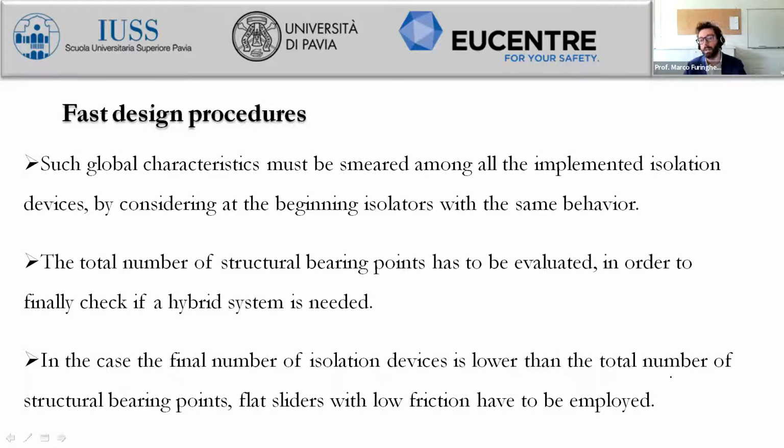So this means that we will have the same constitutive law, which means the same hysteretic rules, and the same mechanical properties and the same geometry for all the isolators. So we will come up with the design of such an isolation system, and then maybe if everything looks like not working properly, we can change some device in order to achieve the optimum of the isolation system.